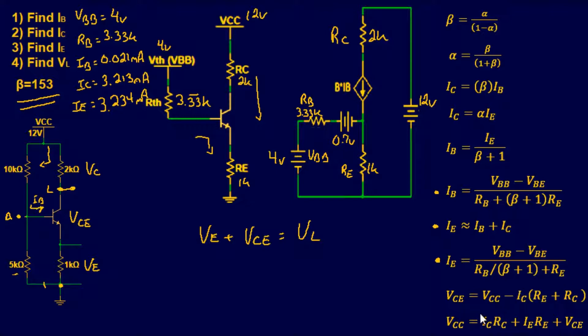Well, we can manipulate this pretty easy, or we could say VC from 12 volts should give you the remaining values right here. So in other words, VCC minus VC gives us our load voltage. Because once the voltage drop across that 2K ohm resistor happens, all that's left is this guy right here.